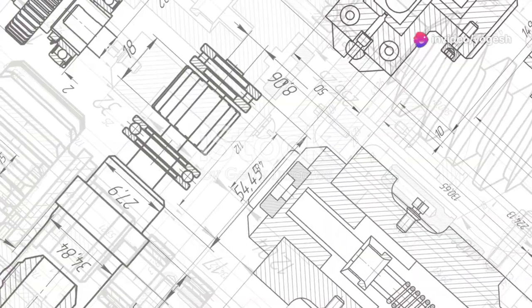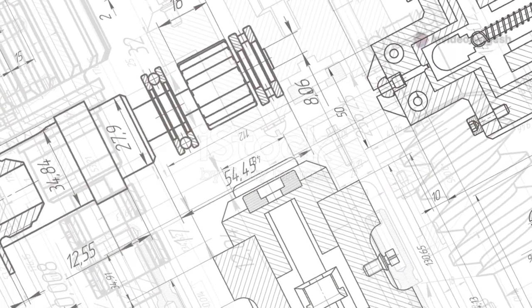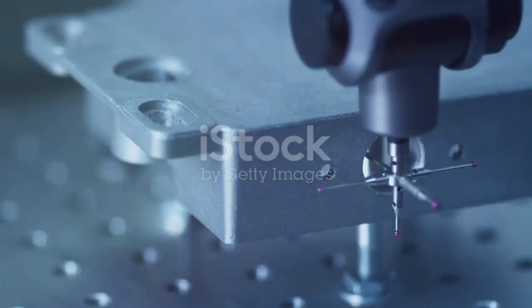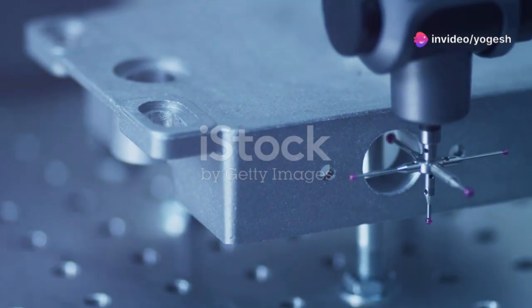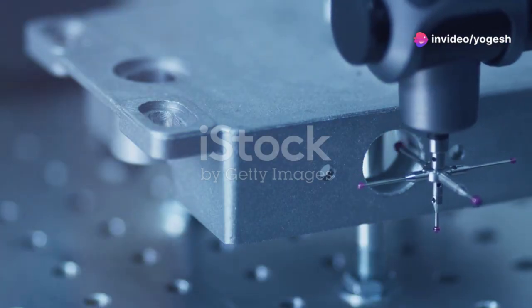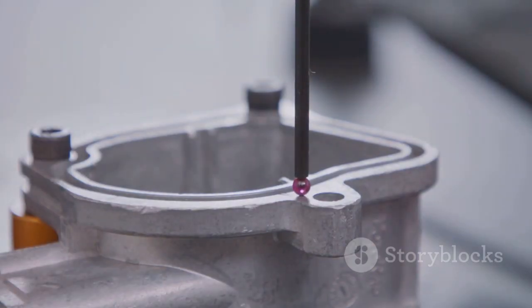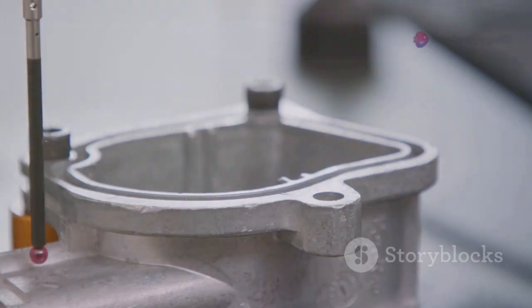Welcome. Today, we're diving into datum targets, a key concept in geometric dimensioning and tolerancing, or GD&T. Not all part surfaces are suitable as measurement references, especially in castings, forgings, or large welded assemblies. Datum targets solve this by designating specific points, lines, or areas for precise measurement, even on rough or uneven surfaces.